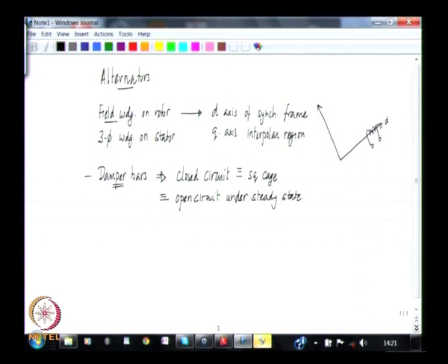During such times there is always a relative movement between the stator field and the rotor, and therefore there is induced EMF in these bars, and since they are closed there is a flow of current in the dampers, which serve to decelerate the machine, which serve to bring the rotor back into synchronism.